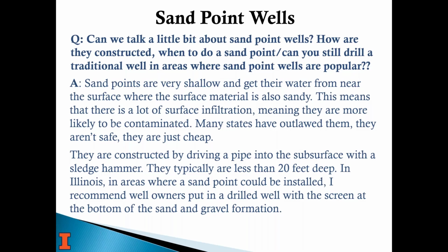If a well owner asks me, and they're in the area where the water level's 4 feet, I tell them they should get a well driller to drill until they hit bedrock, pull up 2 feet, and put their screen right on top of the bedrock in the sand. Sand's a natural filter. It's a farming area, so there's tons of nitrate and pesticides. The cleanest water in that aquifer will be at the bottom, because the water has to go through all of that sand to get there, and the nitrate and all that stuff gets broken down.